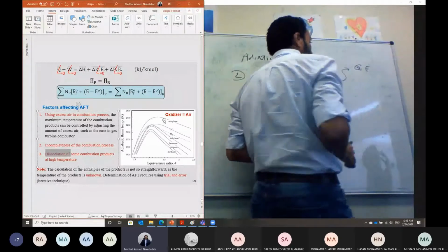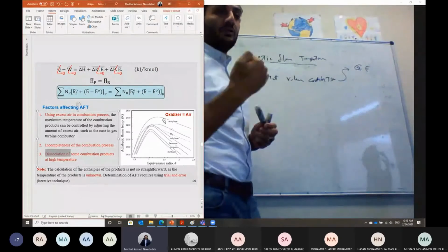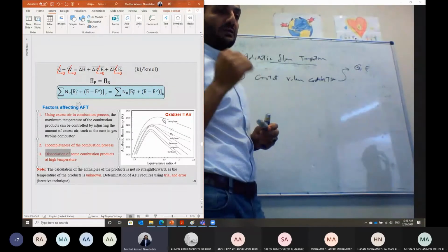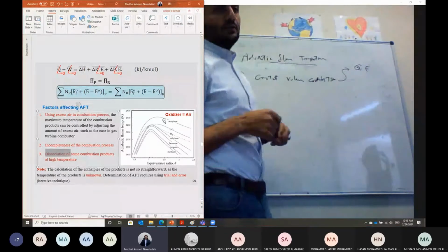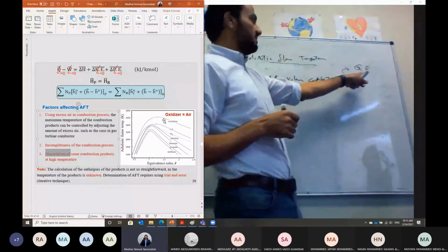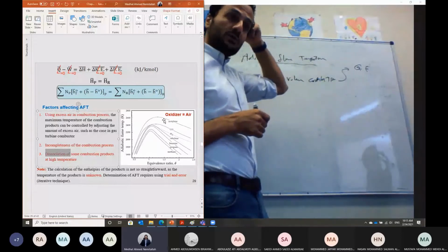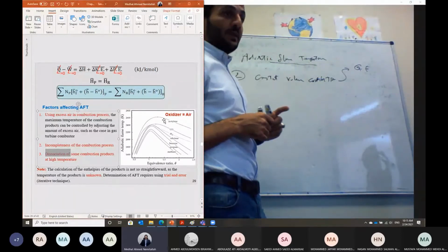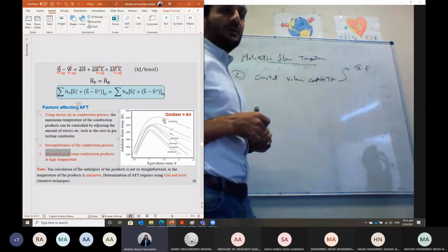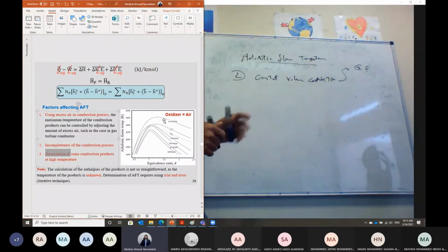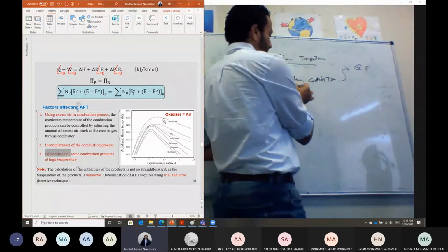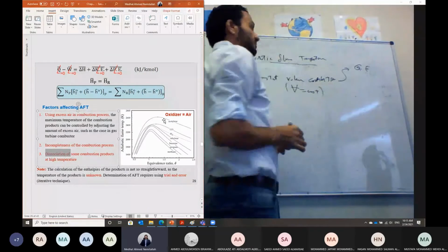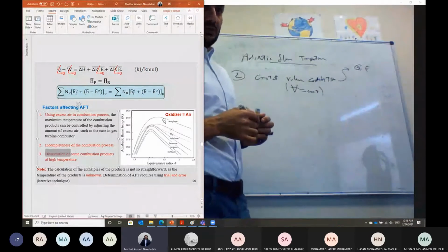When we have a gasoline engine, a spark plug initiates the combustion inside the cylinder, and then instantaneously the combustion is done, so we consider it constant volume. Inshallah, we'll see the cycle of the gasoline engine, which is the Otto cycle, and you will see that in the ideal cycle of the gasoline engine the combustion takes place at constant volume.